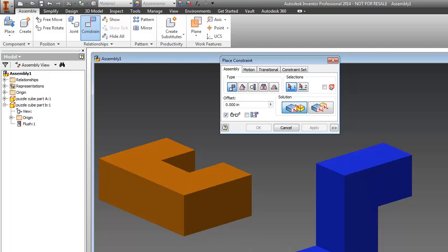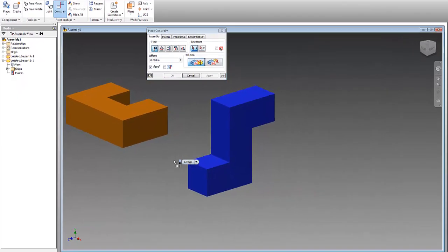Now why surfaces? Because the most stable environment are surfaces. The second most stable item is a line or an edge. And the third is a point. And so we try never to use points because they're the least stable. We can use edges, vertices, or points. Not very stable on vertices or points.